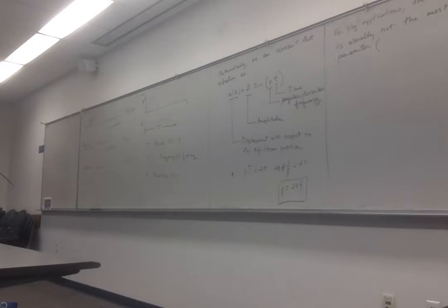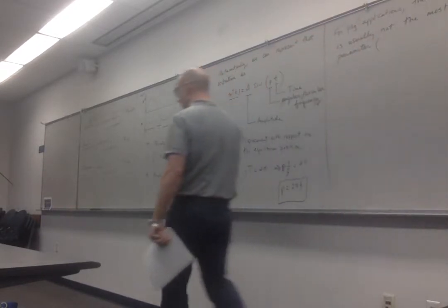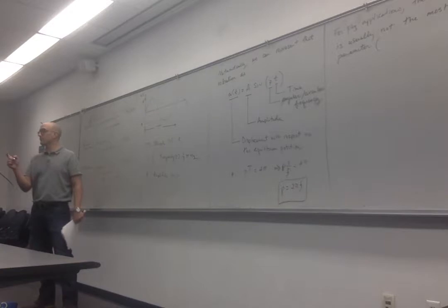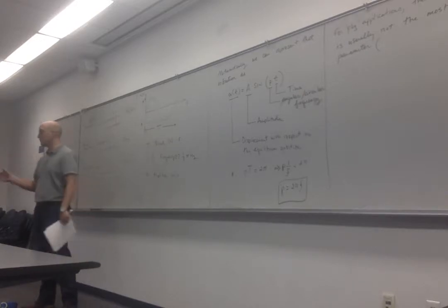Think about it this way. The way to think about a spring and mass system is that the product is the mass and the spring is a cushion. So when do you think the displacement might be important? When the product is thrown on the ground, how much the cushion compresses. Okay, that's good. Actually, this is a good point, because one thing you don't want to be confused about is the following. What is the purpose of a cushion in the packaging system? To dampen the impact. So you use a cushion to protect against shock, not vibration.